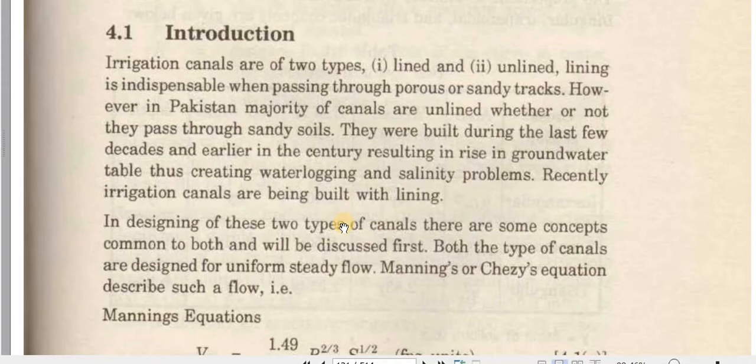For canal design, the most important thing is that a canal should be non-silting and non-scouring. There should be no siltation, no sedimentation in the canal, and there should be no scouring, no erosion from the bed or the banks.